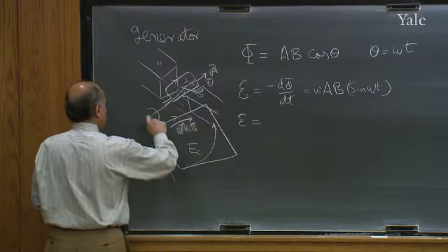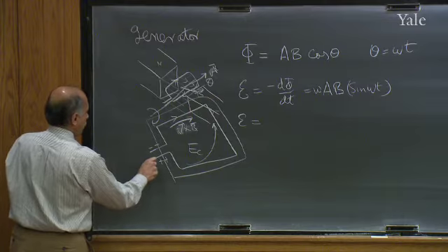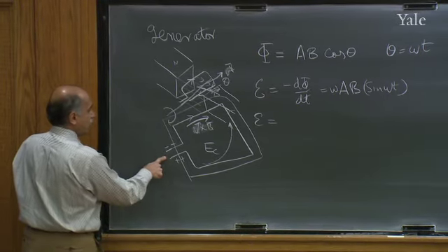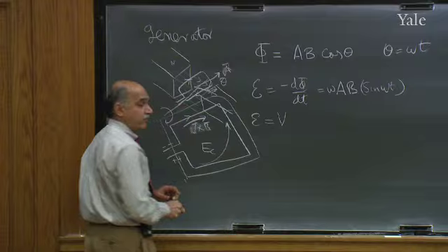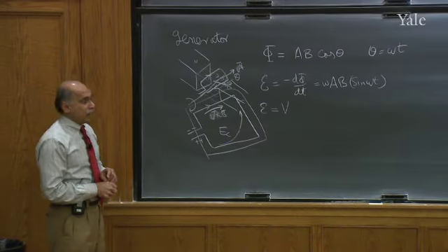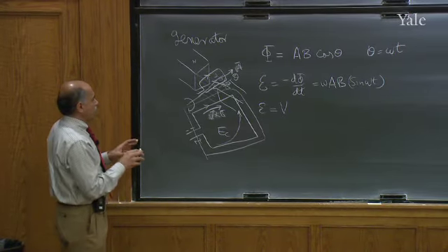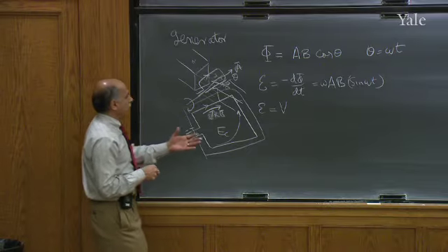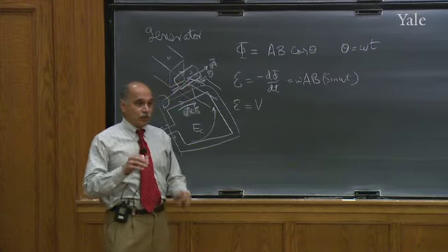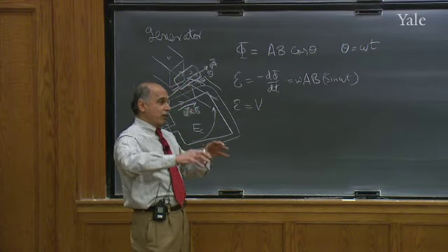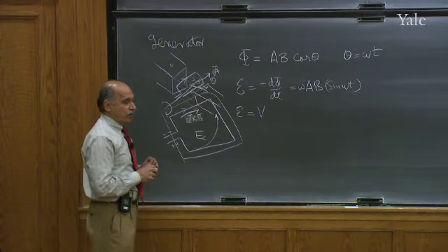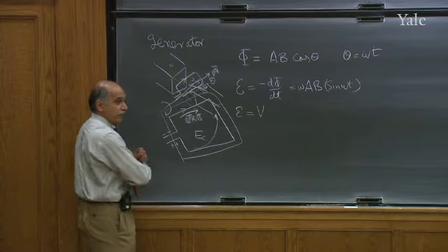But now, if you put the whole thing in a box and you don't know anything and you come outside, what you will find is this will be positively charged, this will be negatively charged, there will be a voltage between these two, which will numerically equal your EMF. This will be that polarity. So I'm giving you an option. If you don't want to look under the hood, you simply say, whenever you rotate a coil, you get that EMF. That EMF is like a voltage. Case closed. But if you really want to know what's happening inside the wire that made up that coil, inside the wire, the net force on charges is actually 0, or an infinitesimal amount is left to make them move this way.